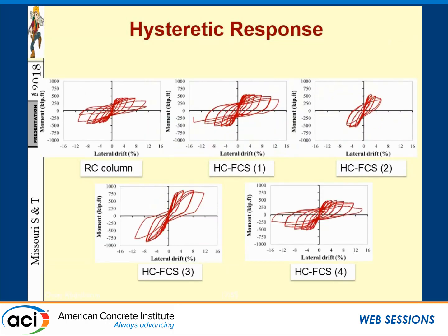This is just a general view of the first phase of this project. This is the reinforced concrete column. And again, nothing here. This is well designed, so we didn't expect any surprise over here. You get a very fat loop with a very high energy dissipation.